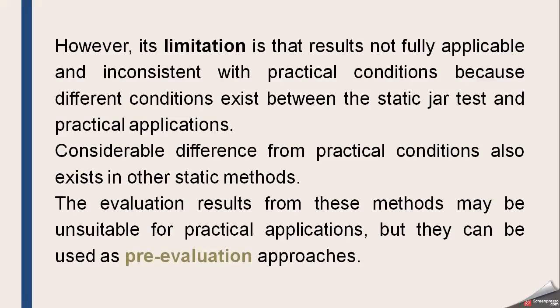Basically, these test methods are not of practical use, but they can be used as a pre-evaluation approach. If we have different antiscalants and different types of impurities, we can use them for indication, and at the first stage evaluate whether these antiscalants are effective against these impurities and other scale forming species. So this is basically a pre-evaluation approach.